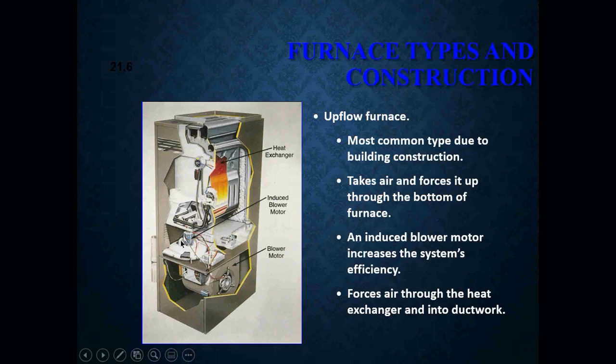The inducer motor helps with the combustion process. It helps pull the flame into the heat exchanger, and it also helps pull the products of combustion out of the heat exchanger and out our flue pipe.